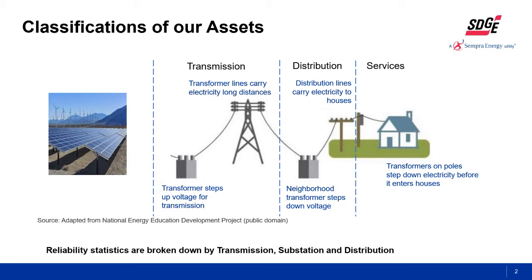Most electric service interruptions occur due to events on the distribution system. So that's what you see on the third column from the left on this diagram, the distribution side. There's generally a lot more exposure for distribution to be subject to problems of one kind or another. So most outages are a result of impacts to the distribution network. Occasionally, transmission events can cause outages, and generation-related outages have actually become so rare they're no longer really tracked anymore.